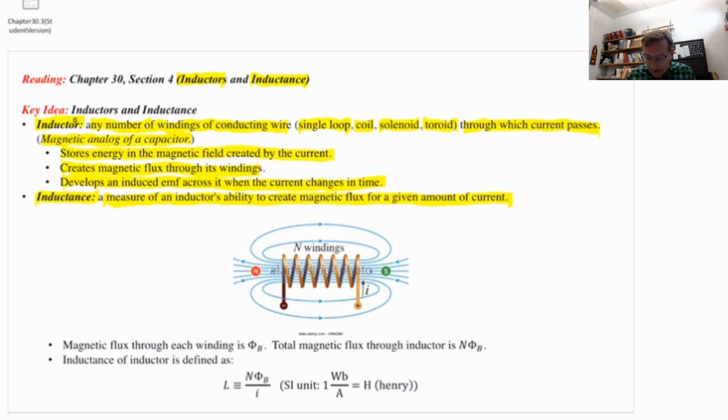We've got conducting wire that we have wrapped around N times, in N loops. You might want to call that a coil, capital N windings. And we're going to pass current, starting over here on the left, going upward, current I. So it's going up in the front, away from us, into the screen at the top, down at the back, and then at the bottom it's coming out of the screen towards us.